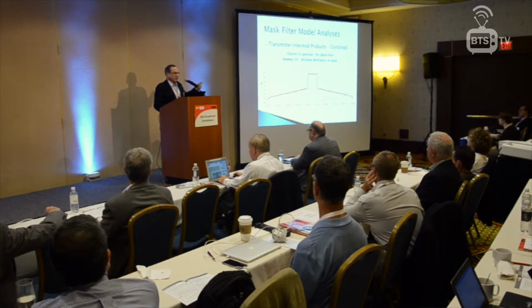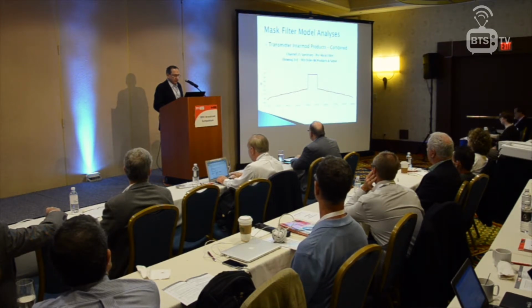The shoulders have to be 47 dB down from channel power, but channel power is up here, and because we're using a 50 kilohertz bandwidth, think of it as a spectrum analyzer resolution bandwidth, in order to look at this, the flat top of the signal ends up 20.79 dB below that. If you add up minus 20.79 dB of power 120 times, you're going to get 1. It'll come to unity, and that's up here at 0 dB. So that's why we have that separation.